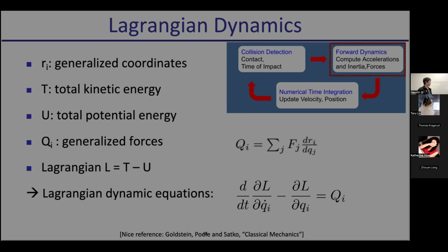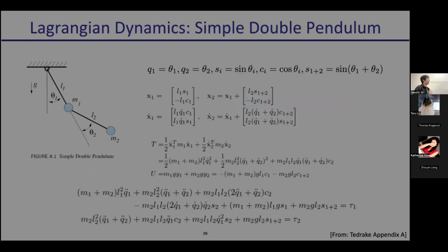So you can get the formulation of what is the torque on each of the joints. And the torque is essentially the accelerations of the rotations. And one example, so you can see very complicated equations, but take into account that you have a simulator and all this mass and length and all these kind of values, including M and L, and also the Q dot, which is the velocities, and Q dot and Q is the velocity and positions of the objects. So all of them are known. They are just single scalars defined by either your URDF or the velocity positions returned by your simulators.